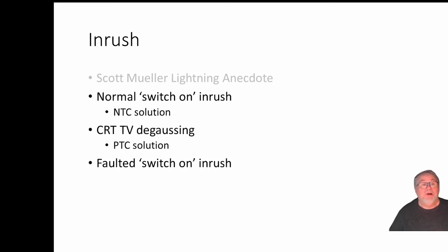But also the shadow mask had a large current going through it because of the actual current that was making the screen glow, and so for that reason it could become magnetized. So in order to stop this, they had a coil of wire around the outside of the cathode ray tube called a degaussing coil. And it was connected straight across the mains via a PTC, positive temperature coefficient resistor. What happened there was when you switched on, this let current flow through, and you got a huge current round about the screen to degauss it.